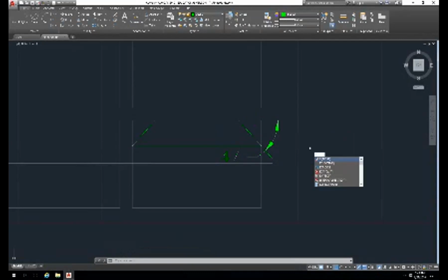So erase, and I can erase this dimension like this, and then erase, select this, and select this as well. I'm going to do control save. Once in a while you see it comes up with a Q save command. So let me figure out this angle once again. So if it's 30 degrees, oh, okay, okay, I got it. There are 180 degrees in a triangle. So 180 minus 30 minus 90. 60 degrees.